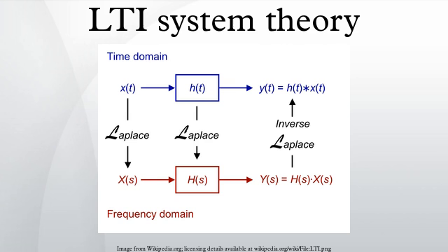Continuous time systems, impulse response and convolution. The behavior of a linear, continuous time-invariant system with input signal x(t) and output signal y(t) is described by the convolution integral. The system's response to an impulse is therefore proportional to a weighted average of the input function, where the weighting function is simply shifted by an amount as t changes. The weighting function emphasizes different parts of the input function. When h(t) is 0 for all negative t, the output depends only on values of the input prior to time t, and the system is said to be causal.